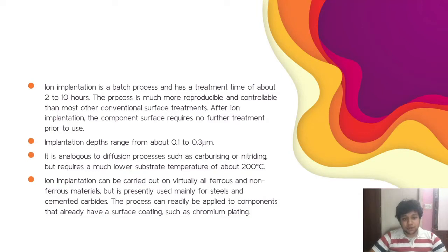The process can be readily applied to components that already have surface coating, such as chrome plating. As I told you, the depths range from 0.1 to 0.3 micrometer, but it is purely independent and we may use any other depths as per our requirements. So it is not a compulsion that the implantation depths must range from 0.1 to 0.3 micrometer, but we have the independent choice to choose our own depths, and we can choose it as per our usage.